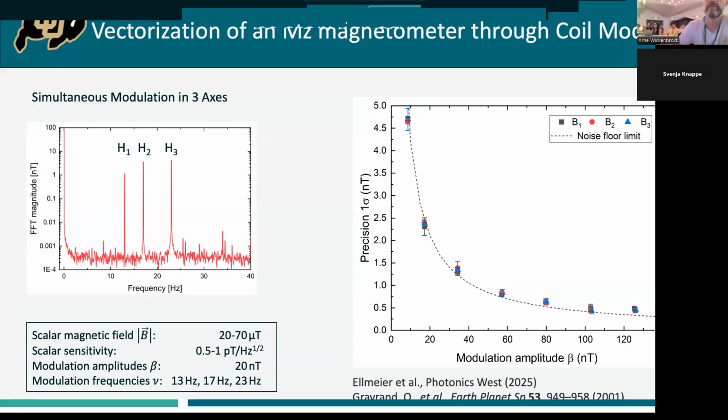If I have a resonance-based one and I jump too fast, then I'm jumping off my resonance. So it is related to bandwidth, but that's where the non-driven magnetometers are really better. If I had a magnetometer that's not in a closed loop, then I don't have that bandwidth limitation. So FID would be better for this particular application. Yes.